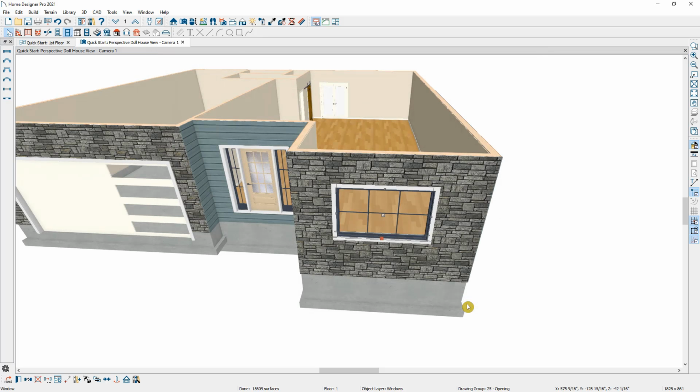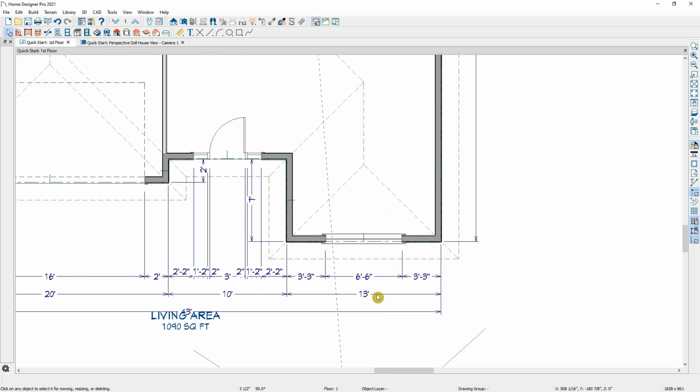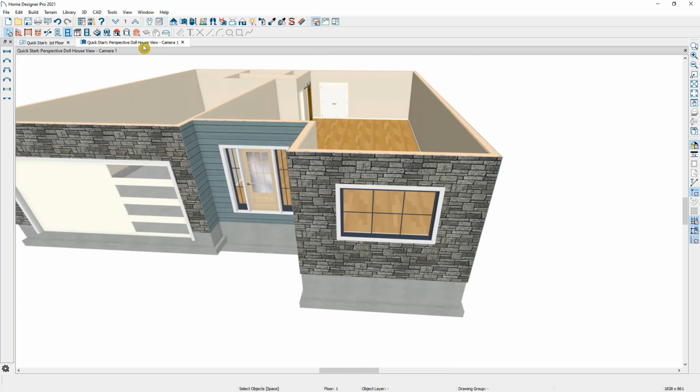and then just click on OK. And then I just want to make sure I have that centered in the wall by using our center object tool and then just coming over to our wall. And there we know that that is perfectly centered. And if you go over to our floor plan view, you'll notice that the program's automatically updated our floor plan to include that window with our dimensions. And if we go back to the 3D view, we can continue adding windows into the plan.